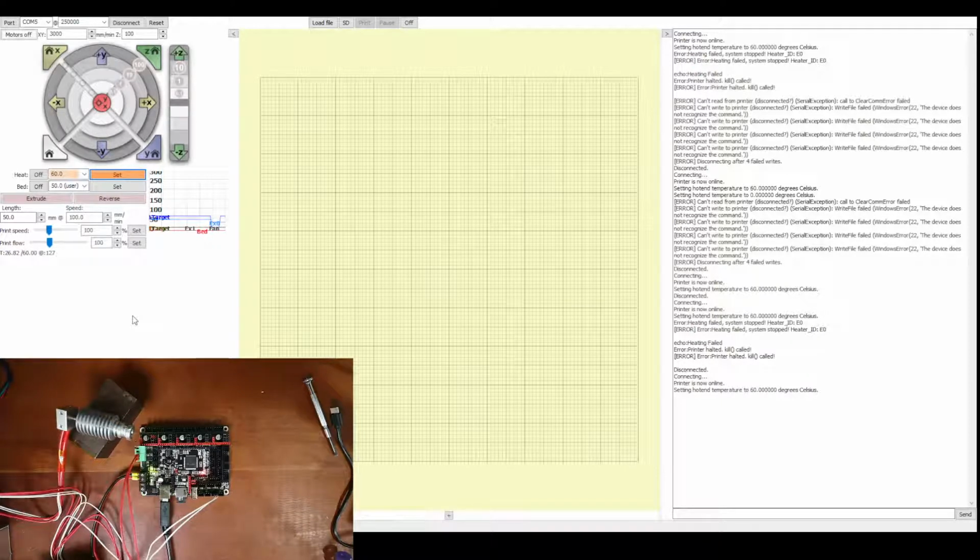So you can tell that the actual power supply is not revving up. So this is going to fail. So we'll give it a second to fail. This is a very unique error. This is why I'm covering it, because I've never seen this before. Usually it's a thermistor that's loose. So you can see that it killed. So that's good.